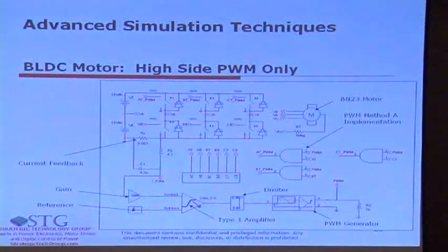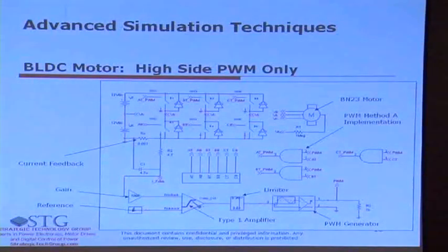Okay, no, I think you're correct. You're correct. We just need a triangular signal. And what we have demonstrated is how we generate the triangular signal. Yeah, triangular part I understood. Right, PWM part also we are generating with some equation. So once we have a triangular signal and the duty cycle setting, the PWM is just a comparison between these two things. Yeah, you're absolutely correct.